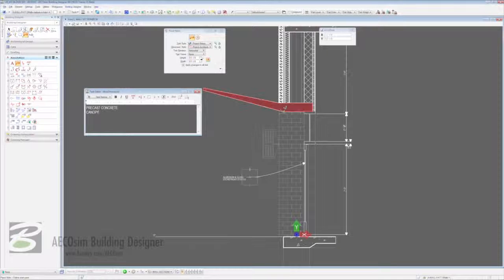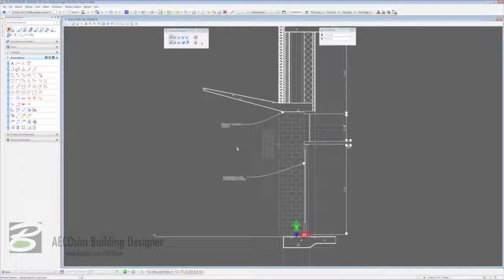And we're going to click at the base of that canopy there. You see AccuDraw and AccuSnap helping us out to place those very accurately. And we're going to click there too. Right click to reset, and there we have it. So we have dimensioning, we have notation, we have notes, we have industry standard line work applied to this, and we've now applied it to a sheet.